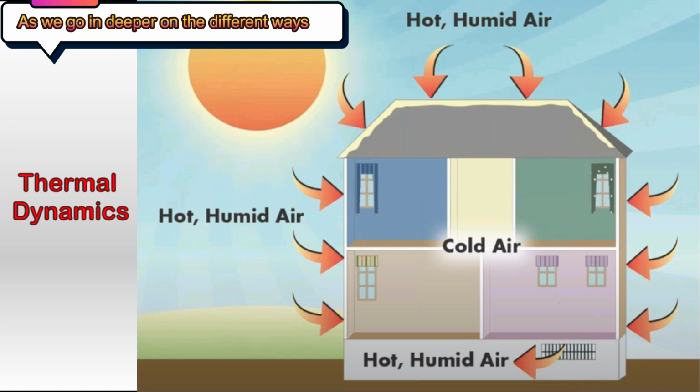As we go in deeper on the different code-approved ways to condition a crawlspace to manage moisture, we always need to keep in mind this thermodynamics law. Hot goes to cold, wet goes to dry, and high goes to low.